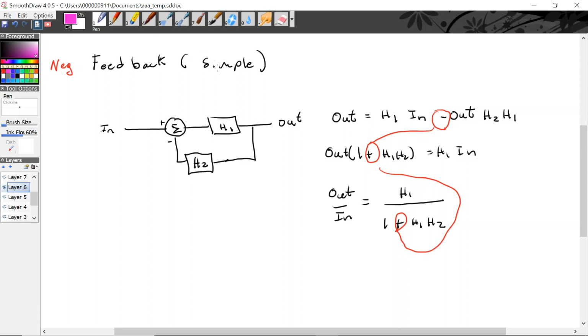So, now we have the series and the parallel, but now what you haven't seen, right, is feedback. Now we have a summer here, and we know what that is. It's just a summer circuit, right? H1, we know that can be an RC with an op-amp, RLC with an op-amp, and pulling the output off the resistor, the capacitor, the inductor, whatever.